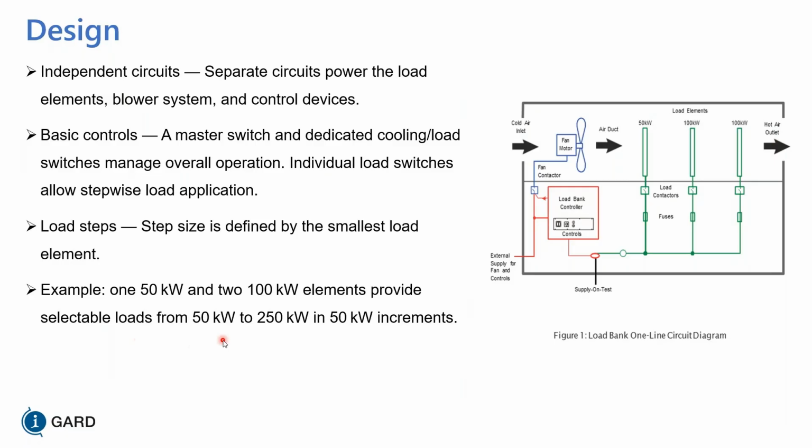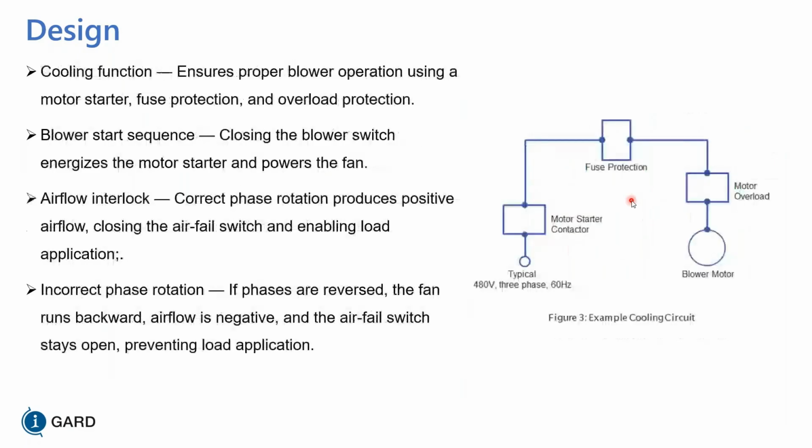So this particular load bank has 50 kilowatt resolution. We can go down to 5 kilowatt resolution. But now you just need a smaller contactor and a smaller fuse. So you don't want to go too low because, if you have a 2 megawatt load bank, you really don't want 1 kilowatt resolution on it. So you have to be practical about this.